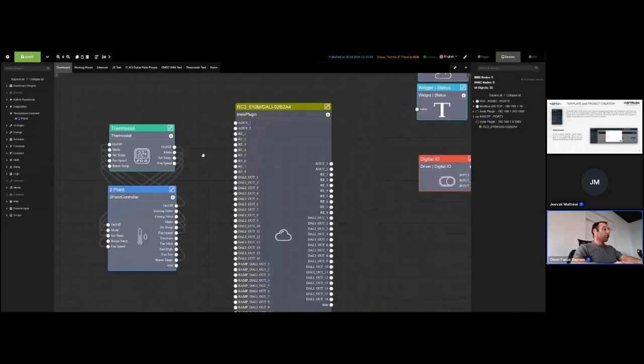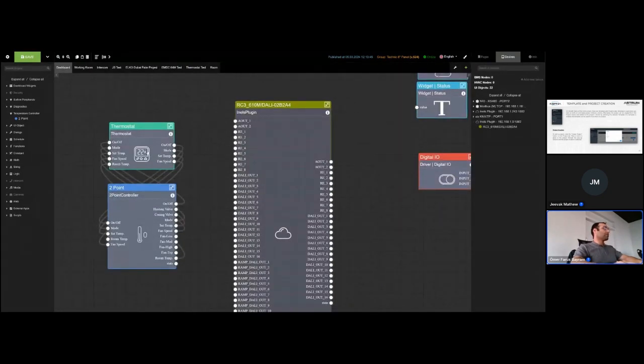As we said before, every object's right side output, we can say feedback side. So we are going to set our command from the input side. For example, relay 1 will be heating valve, relay 2 will be cooling valve, and the others, for example, 3, 4, 5, 6 will be for low fan, mid fan, high fan, and top.